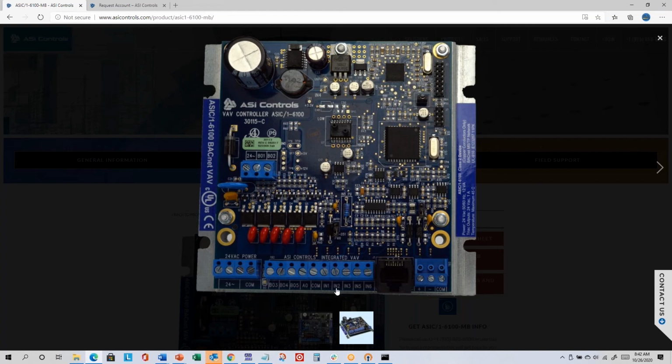And so in inputs 1, 2, and 3, if you're using the communicating wall sensor, you would not use those screw terminals because those signals would be coming in through the RJ45 jack. This looks like an Ethernet port, but it's not. We've been using this RJ45 jack since the first controller we ever made as an easy way to get 8 wires from the controller to the wall sensor.